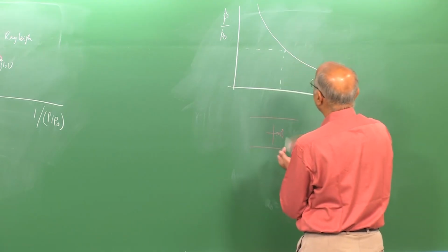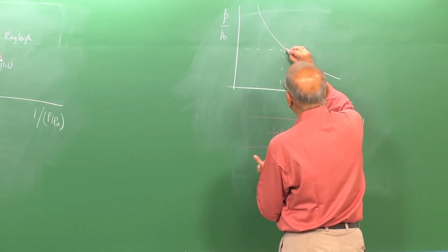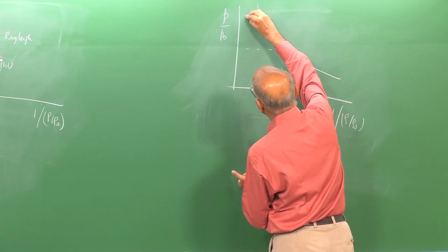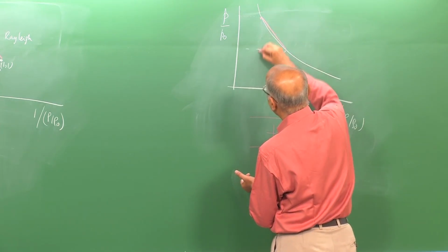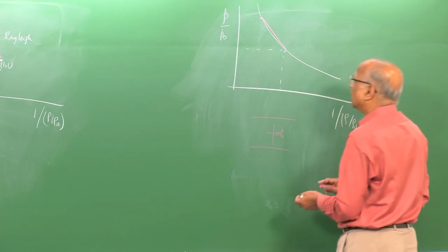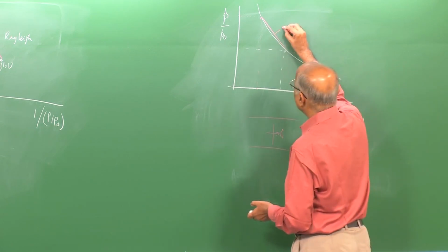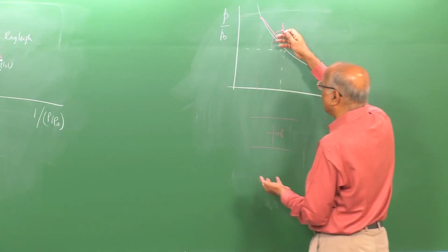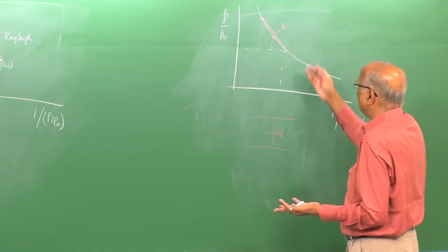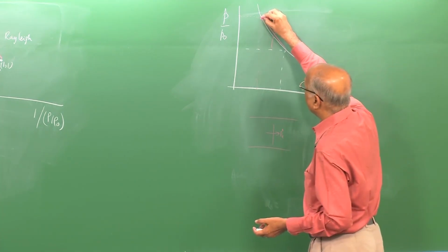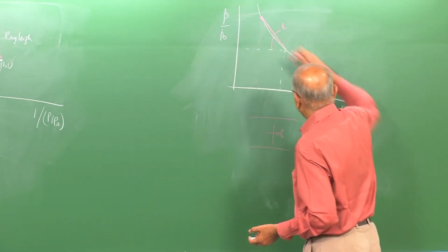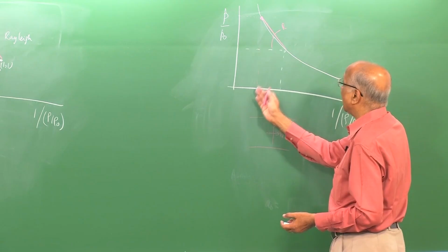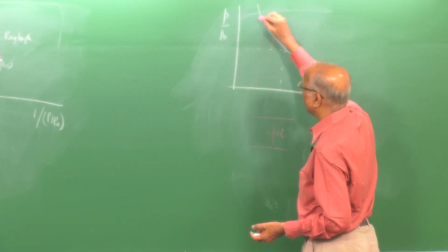For a given value of Rs dot, I have only a particular value of velocity which hits here, and this is my value of pressure and this is my value of density. Therefore, by solving the Rayleigh line along with the Rankine-Hugoniot equation, or the shock-Hugoniot equation, both are same, I am able to get the final point, the final pressure and the final density, because the initial density is known, and I can get the properties of my medium.